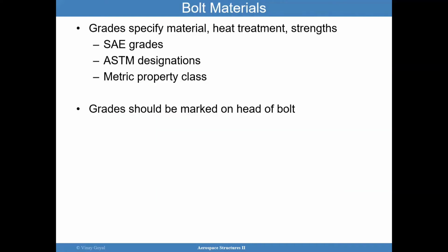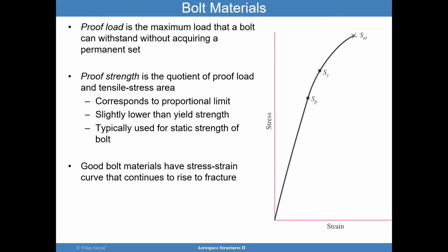So, bolt materials. I'll explain later how this information is used, but grade materials will specify heat treatment strengths, and the grades will typically be marked on the head of the bolt. I want to point out a few things here. With bolts, if you have a lot of bolts, it's good to test one of that lot to make sure that the lot is good. There are things that should be considered here.